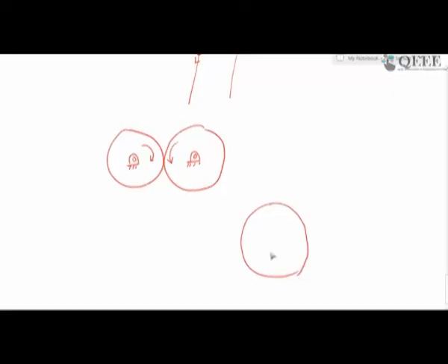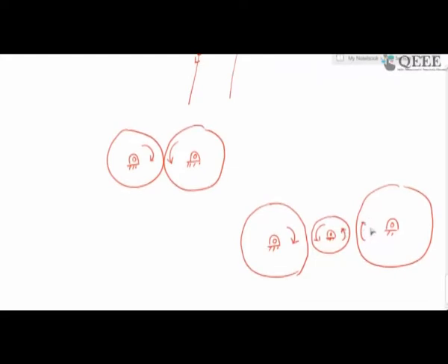So if you have an idler gear in between, the gear ratios will remain unaffected, but the direction will be reversed. Here if you have the input to be clockwise as usual, then the idler gear will rotate anti-clockwise, and if it rotates anti-clockwise, this will rotate clockwise. So what you have achieved is that the output is taken from this shaft.